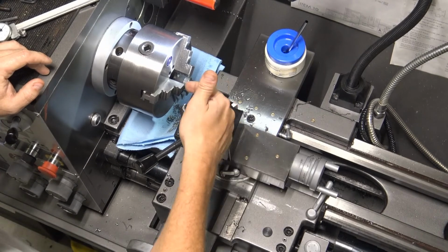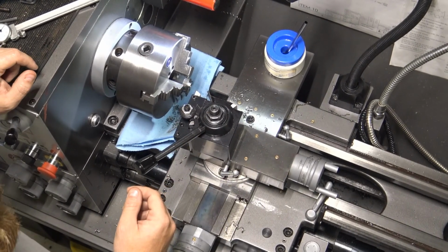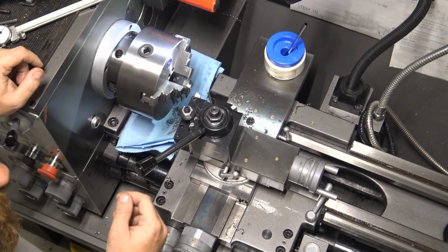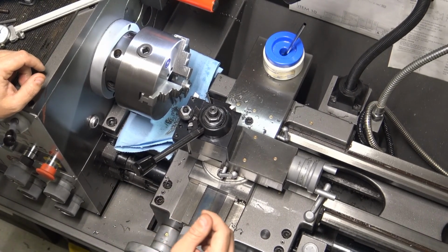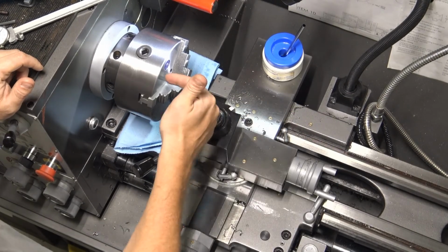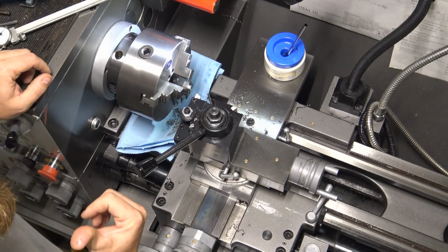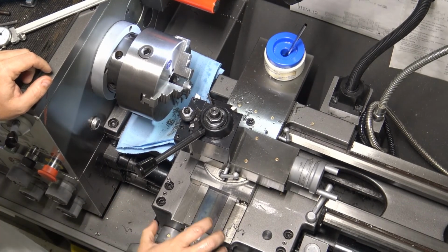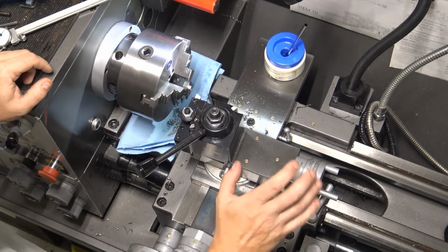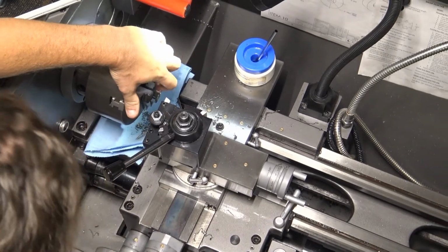If you leave the tool in there while it's spinning, you're just going to generate heat, and it's going to break down your tool and ruin your part a little bit. So I know that I'm going to go in 190 and then straight back out in the X. I'm where I need to be on my X right now, so let's do that final pass.